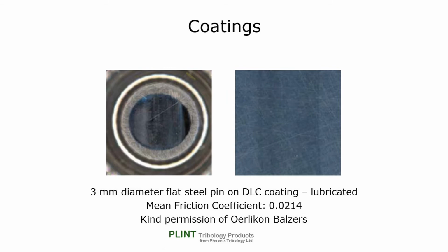In addition to significant differences in both wear mechanism and wear rate, the steady state friction coefficient with the area contact, in this example, was 0.0214, compared with a steady state friction coefficient of approximately 0.07 for the Hertzian point contact test.